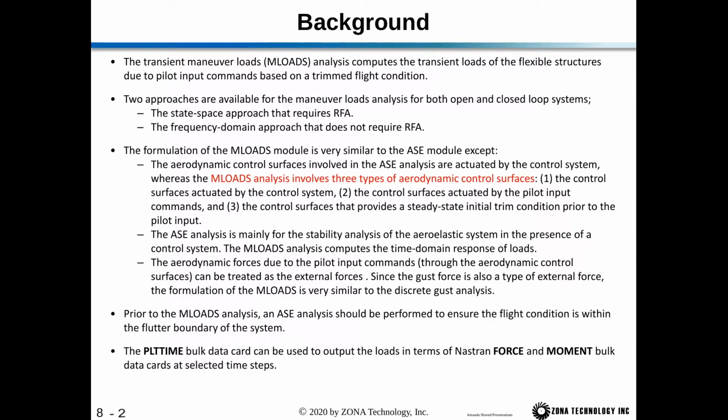If you try to do a maneuver loads analysis that's outside of the flutter boundary, that is where the system is unstable, then of course your time domain analysis, your states are just going to blow up and go towards infinity. So it won't be a very useful analysis.